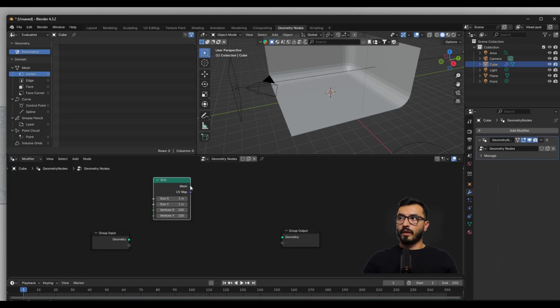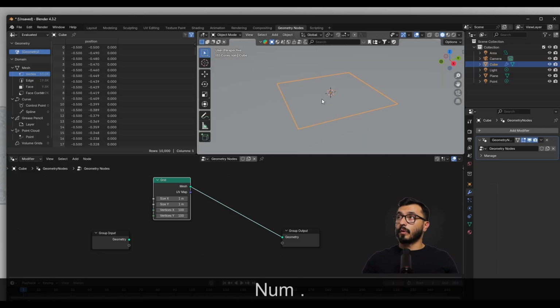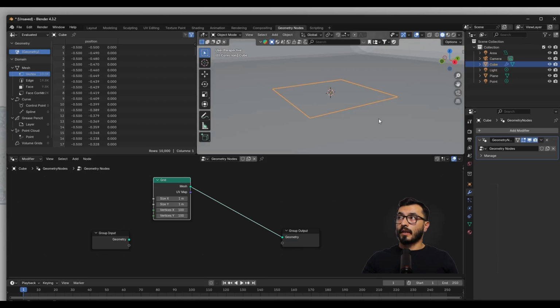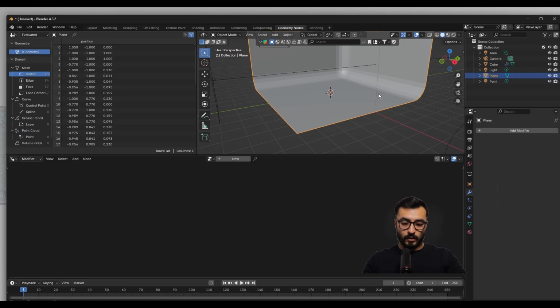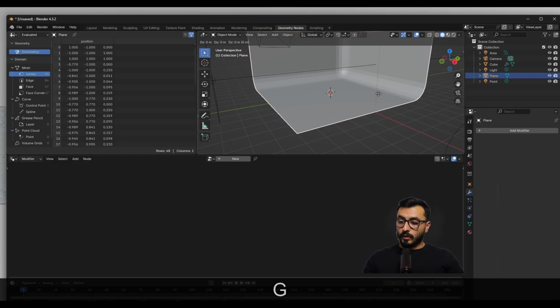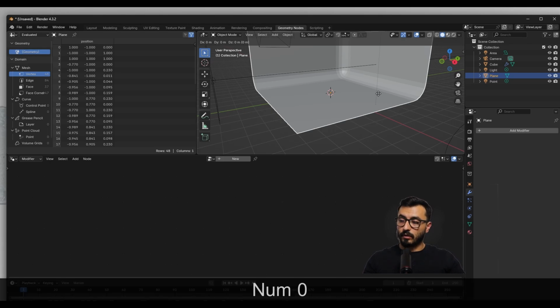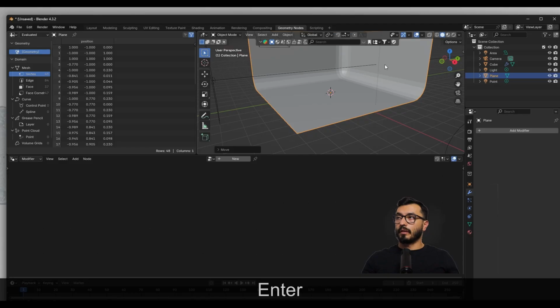If we connect now the mesh to the geometry, we will see that what we have is something like a plane. Let us move this box a little bit to the bottom so that it doesn't interfere with our geometry. So let's grab it minus 0.001, and that will be enough.